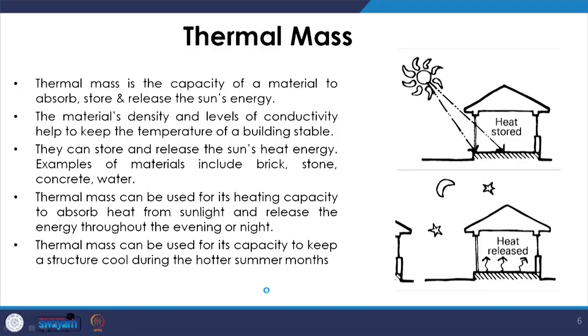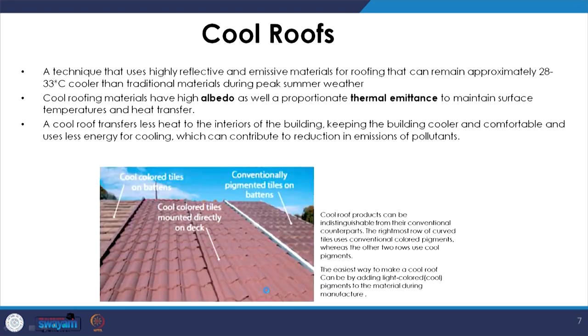If we are looking at thermal mass as a strategy, here the mass will absorb the heat and it will re-radiate it during the night time, or the time when the temperatures fall below the surface temperature of the material. So, this strategy is often utilized as a very popular passive design strategy when we are designing for extremely high temperature variation, high on heat or high on cold.